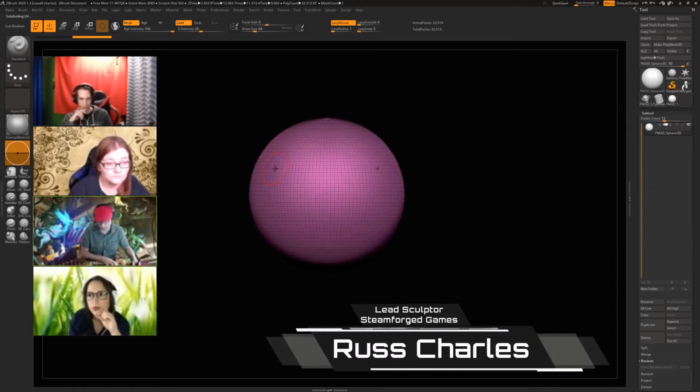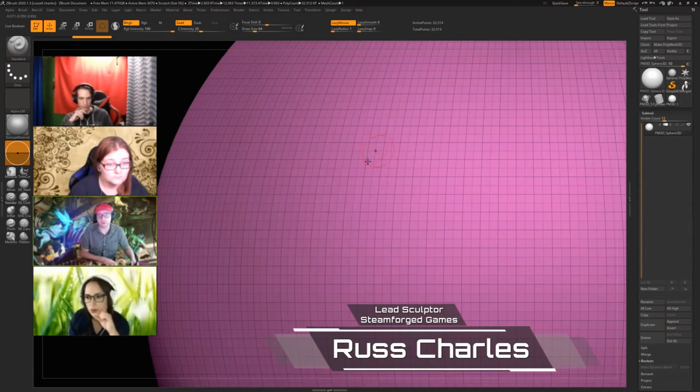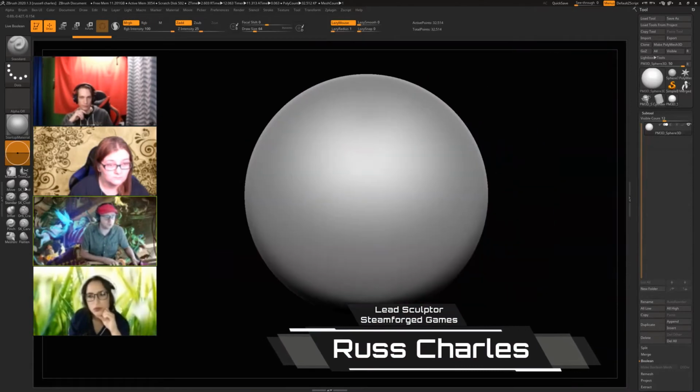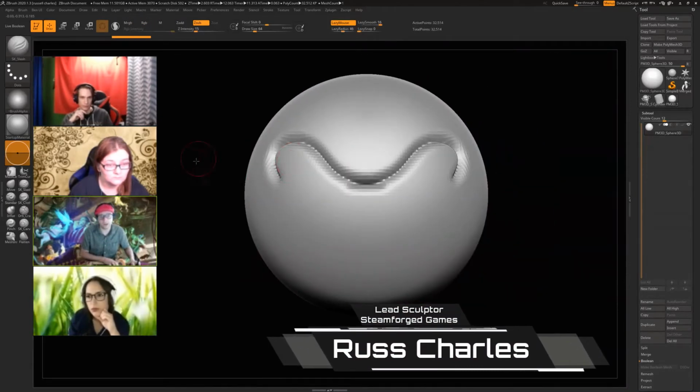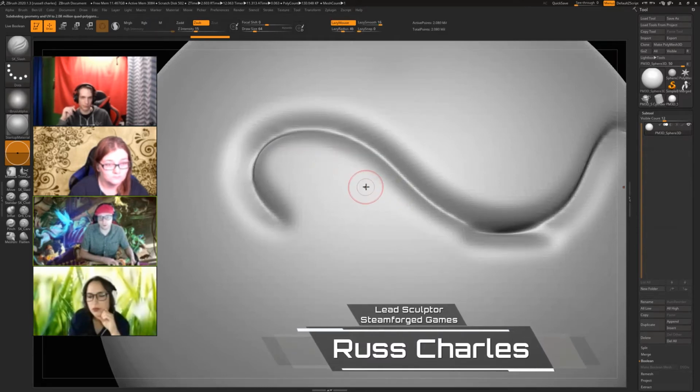where you'll have an object, and everything in all of the programs is made up of different sized polygons, which are these little squares. And basically, the more detail we want to add, the finer we divide this down. So if I were to draw on this right now, we can create a curve, but you can see the individual pieces deforming. If I subdivide that, I can increase the number of polygons we have, and that will go smoother and smoother as I divide this lower and lower.